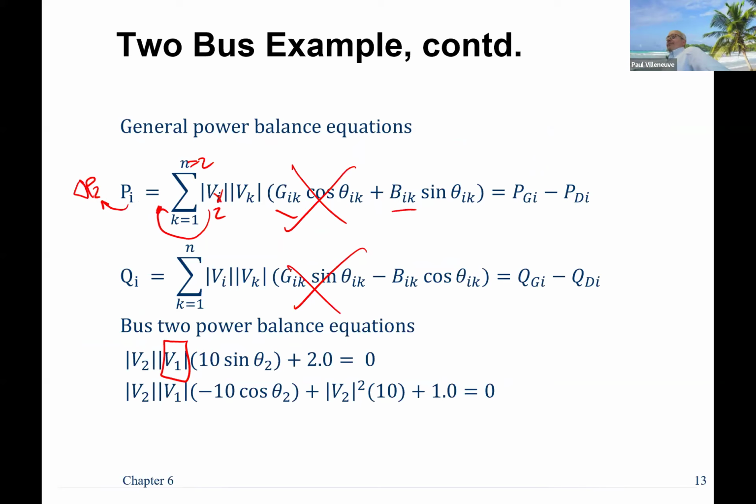In this case, we're looking at bus 2, so you have to check everything from bus 1 up to bus 2. That's why K goes from 1 to 2, but I is fixed at 2, because I never changes. You're looking at bus 2. Correct. You're looking for delta P2. P2 and I are the same.